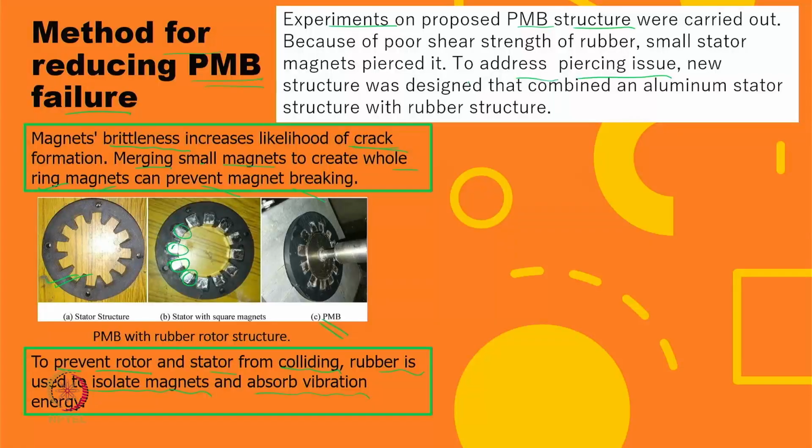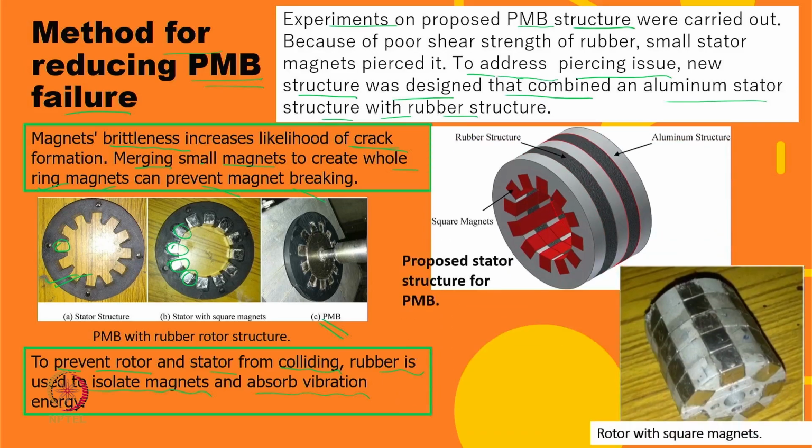That means a permanent magnet, they start piercing into this shape itself. So, cracks developed in the rubber material, and once the rubber is cracked, it will not have that kind of flexibility. So, again the major problems will come. For this purpose, instead of going for rubber alone, we should have an aluminum housing with a rubber material and permanent magnet. The new structure was made, and then finally a patent was filed on this, and we got good results.